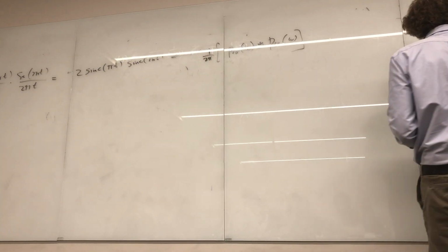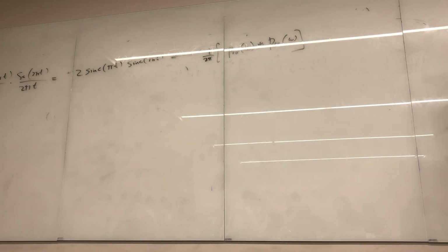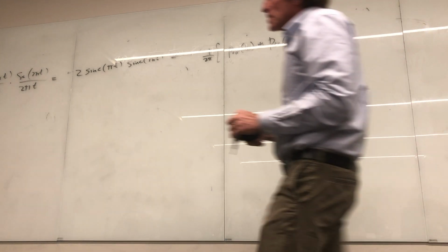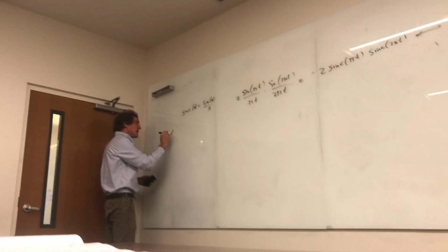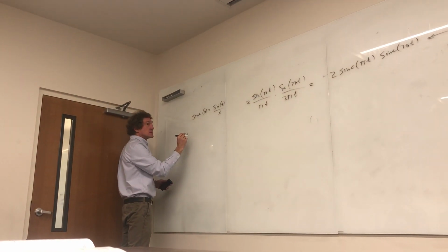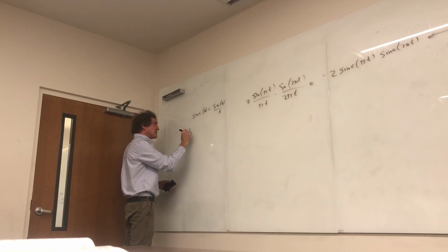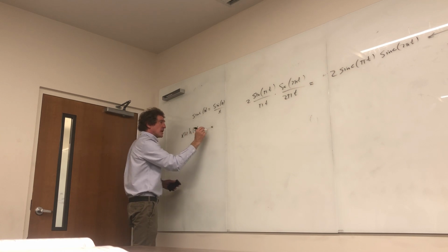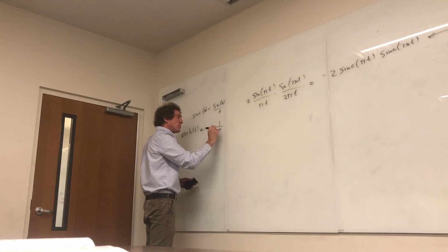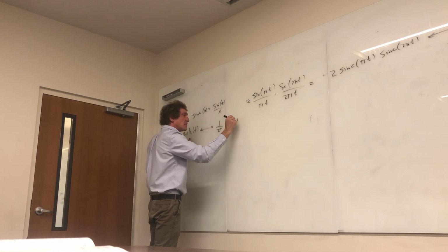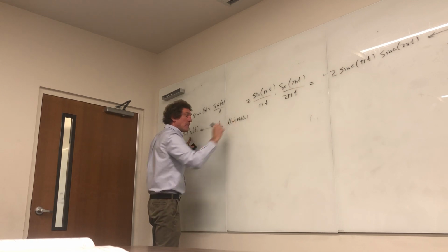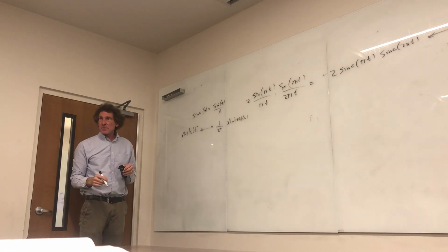Now, we're going to do the convolution. Wait, hold on, why isn't the 1/2 only on the 4 pi pulse? So you can see it right here. This is the property of it, right? x of t times, I'll call it h of t. The transform of that is 1 over 2 pi times x of omega convolved with h of omega, okay? That's what it is, all right?